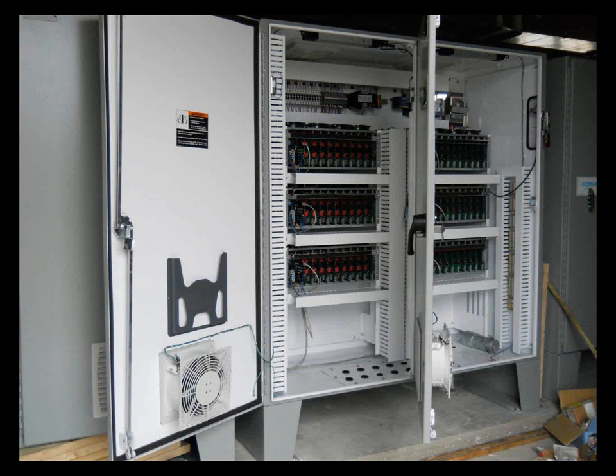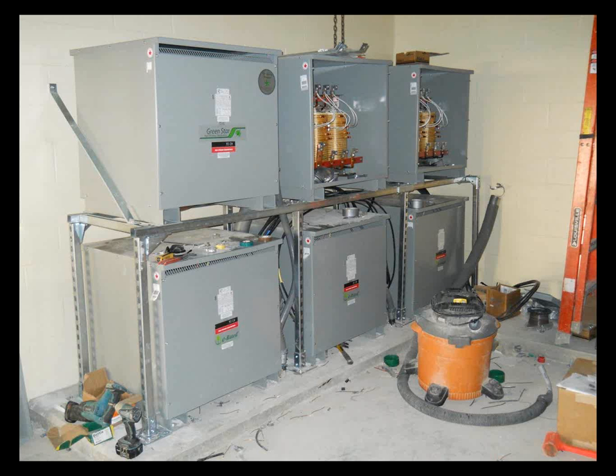Here is one of our ballast cabinets. Each one of those little black deals with a red clip is a ballast, and each bulb has a ballast. You do not need an electrician to replace these ballasts. You just unplug, pull out, slide a new one in, plug the cord back in, just a few minutes, and an operator can do this.